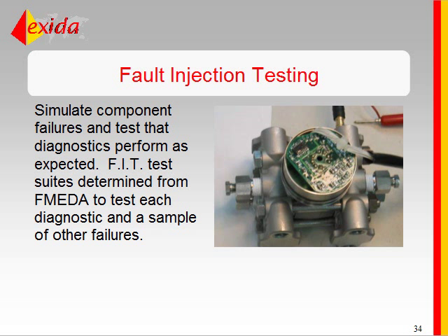But in fault injection testing, you go in and come up with means to simulate component failures. Like if resistor R7 fails short circuit, that's easy. We just short circuit resistor R7, typically with a little pair of sharp needle nose tweezers. And we check to make sure that the instrument performs exactly as the FMEDA predicted. FMEDA is actually used to generate a set of fault injection tests, and when the fault injection tests are run, we confirm the accuracy of an FMEDA.